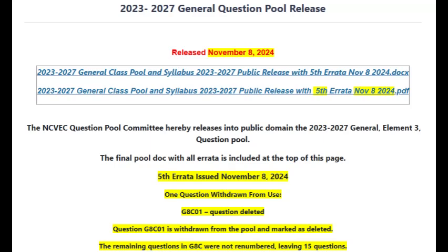G7A07A. What is the output waveform of an unfiltered full-wave rectifier connected to a resistive load? A. A series of DC pulses at twice the frequency of the AC input. B. A series of DC pulses at the same frequency as the AC input. C. A sine wave at half the frequency of the AC input. D. A steady DC voltage.